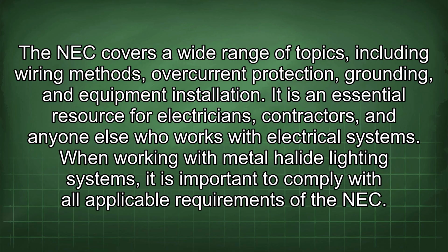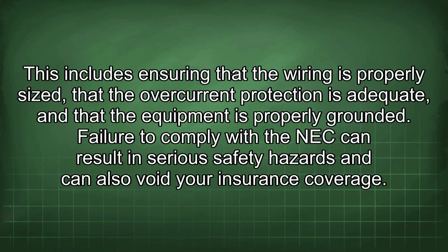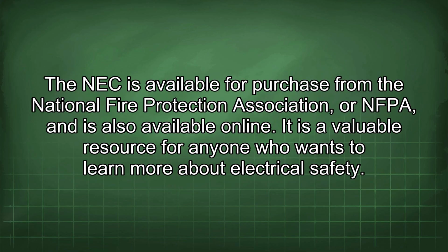When working with metal halide lighting systems, it is important to comply with all applicable requirements of the NEC. This includes ensuring that the wiring is properly sized, that the overcurrent protection is adequate, and that the equipment is properly grounded. Failure to comply with the NEC can result in serious safety hazards and can also void your insurance coverage. The NEC is available for purchase from the National Fire Protection Association, or NFPA, and is also available online. It is a valuable resource for anyone who wants to learn more about electrical safety.